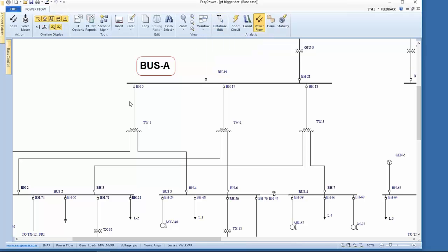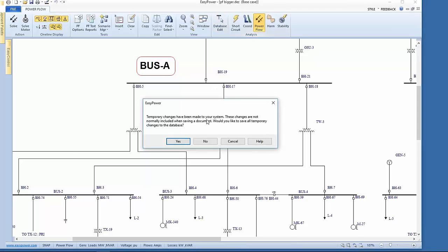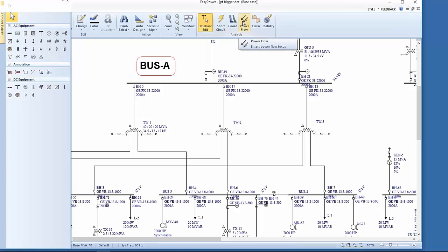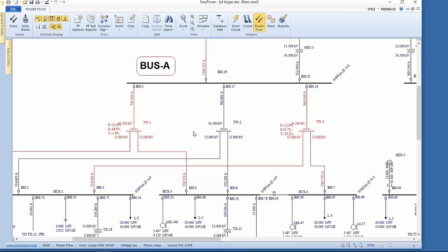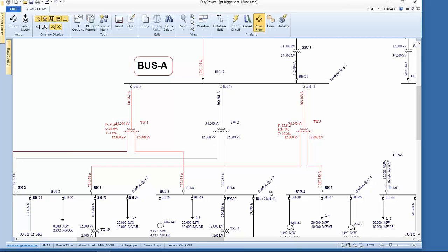Now the point being that this is a breaker that I had open, and so a logical progression would be, if I go back and try to open this again, now with that breaker closed, if my PowerFlow solution now resolves, clearly that was a source of my problems. And as soon as I do that, I can see I have some control warnings that make me realize trying to resolve the problem with that breaker open is not a good idea. So let's talk real briefly about what we're indicating.